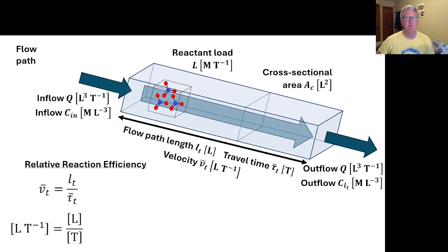Assuming steady-state plug flow conditions without longitudinal mixing, travel of parcels of water along the length of the flow path will be associated with a single characteristic transit time, determined by the average velocity of flow. The average velocity provides a dimensional map from a transit time to a distance traveled along the flow path. A longitudinal reaction rate coefficient can be derived by dividing the temporal reaction rate coefficient by the average velocity.